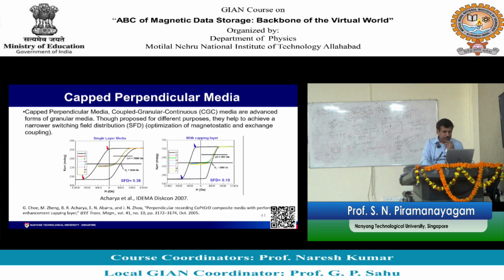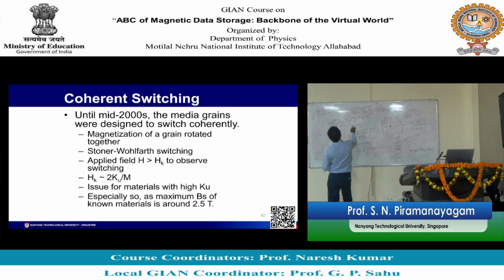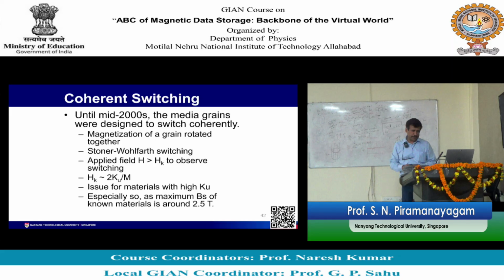Okay, so let me skip some of this. The oxide does not stay as oxide. I mean, your target will have oxide, but when you do sputtering, you are not maintaining this oxide. What you have is that oxygen goes into the grain boundary. So, your grain boundary is oxygen rich, the grains do not have oxygen. So, you have magnetic region and non-magnetic region.